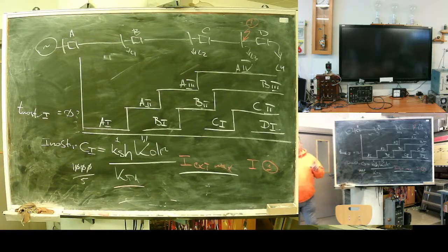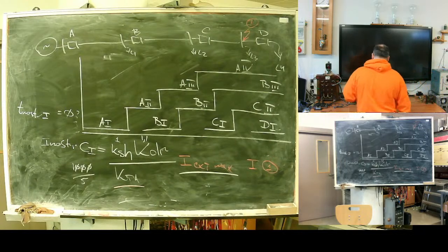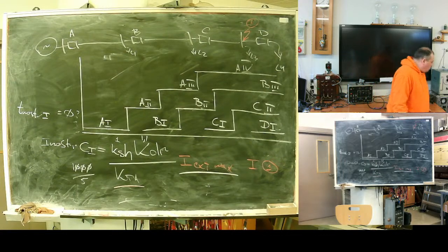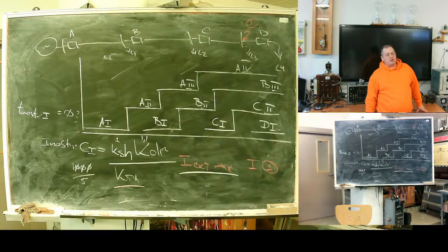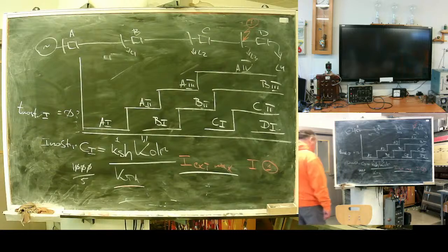There is one moment. Old books say 0 means instantly, operates instantly. In modern life, you cannot operate instantly, but you can set a trip time, for example, 10 milliseconds. Actually, with a masochistic approach, you can have a trip in 1 millisecond. It's not good. I'll tell you where the problem is.